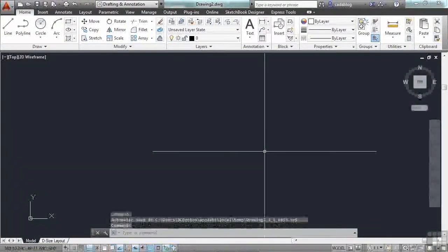a closed multi-sided shape. You can create a polyline with several different commands: pline or p-line, rectang, polygon, donut, boundary, and even rev cloud. Pline or p-line, depending on how you want to say it, because it's just the letter P, then L-I-N-E. That will be your most commonly used command to draw a polyline with. And we'll talk about the other options in a later section. Each of them has its place.